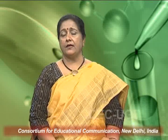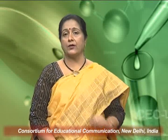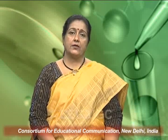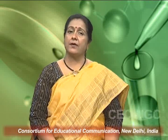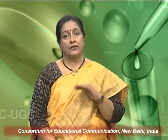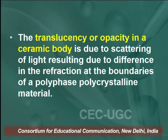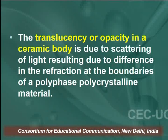These impurities cause color centers in normally colorless material because of the non-stoichiometry in the cation-anion ratio. The translucency or opacity in a ceramic body is due to scattering of light resulting from the difference in refraction at the boundaries of a polyphase polycrystalline material.